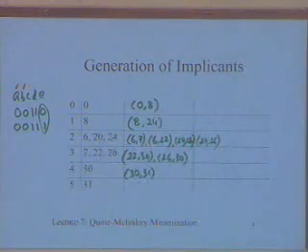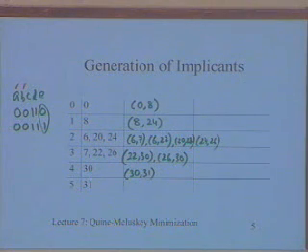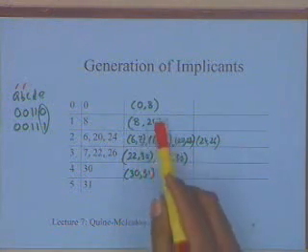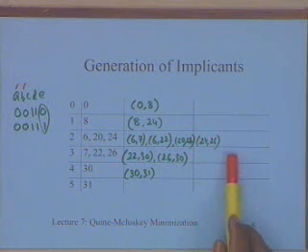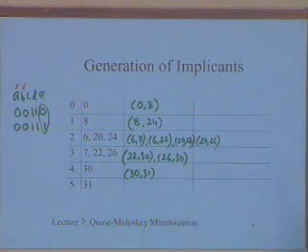So if you look at the Karnaugh map equivalent, I am now trying to make a box of 4. Here I had tried to just combine 2 terms, and now I am going to combine 4 terms. So I am going to make a box of 4, and similarly if I have more stages I will make a box of 8 or 16 or whatever, if I get enough terms to do that.